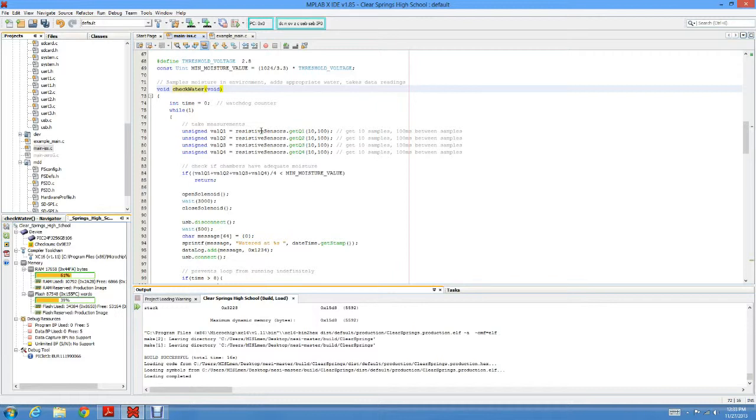Let's say, for instance, whenever we called read Q1, a spike occurred in the output. That would then give us invalid data, where we think it's higher than it actually was. By sampling it over a time period, we're able to filter out all of the spikes or dips and actually get the correct value from the sensor.